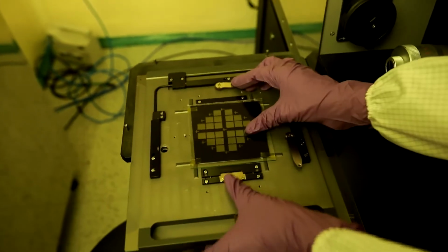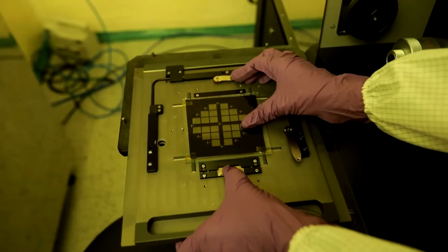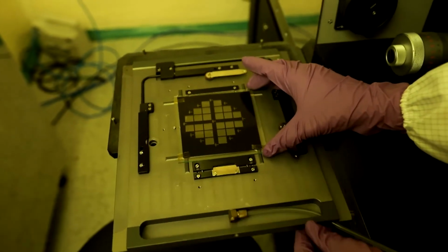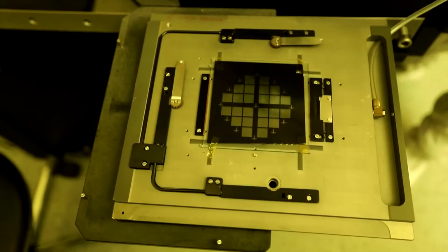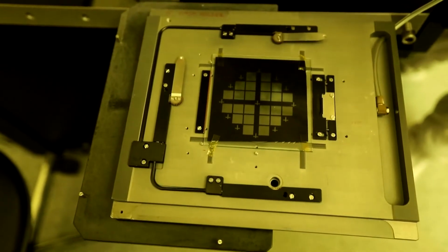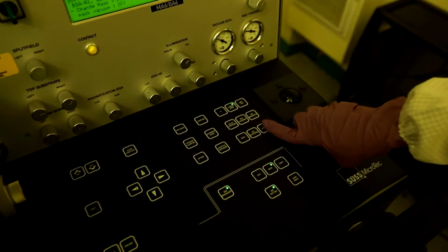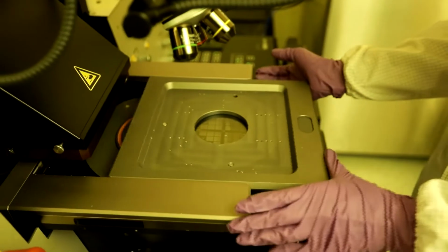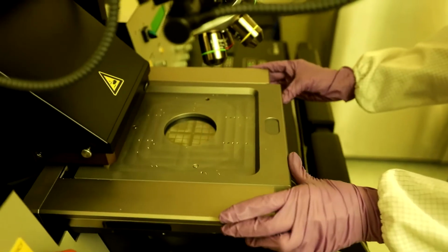Release or pull back the mechanical lock and keep the clean photomask in the slot of this holder with chromium-coated side facing upward. During exposure, the side will be making contact with the sample. Press Enter to allow the vacuum to hold the mask plate. Keep back the mask plate holder in its slot and press Change Mask to lock the mask holder in its position.